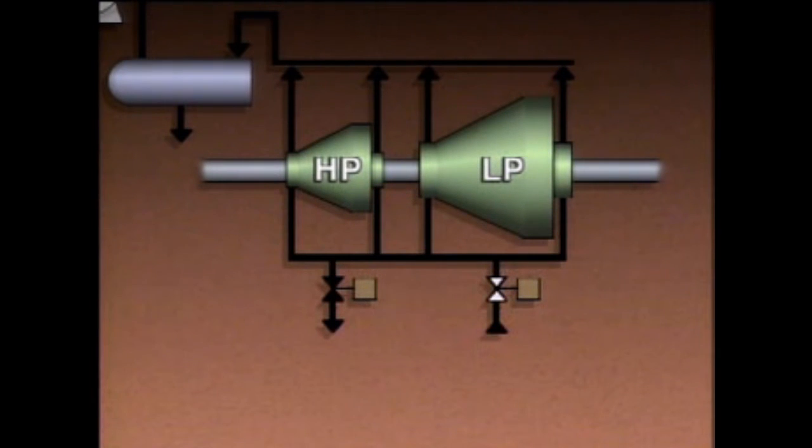When the turbine is operating at full load with a positive pressure in most of the turbine, air leaking in is not a problem, except near the last stages, which are still under a vacuum. Where the pressure is positive, steam must be prevented from leaking out. In this case, pressure in the gland is increased by steam leaking from the turbine. The steam supply valve closes because steam no longer needs to be supplied from outside the turbine.